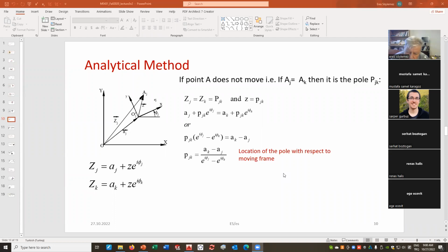Usually in geometrical methods, we use 2 points A, B on the moving body to describe its location and determine the position of a rigid body. In analytical methods, it's preferable to use the moving coordinate frame.